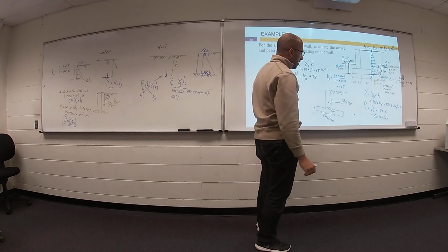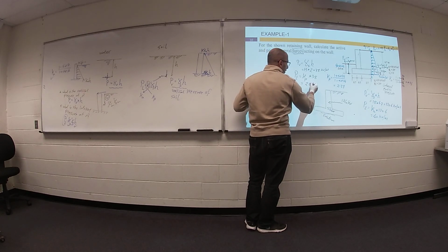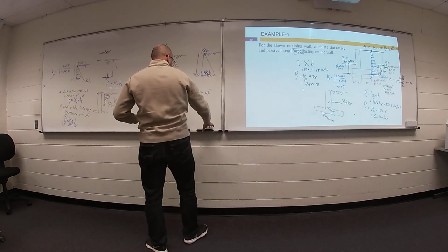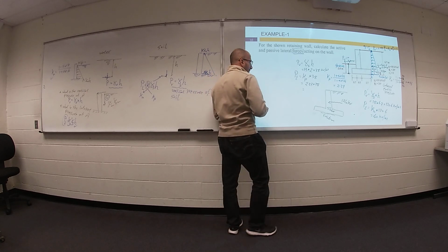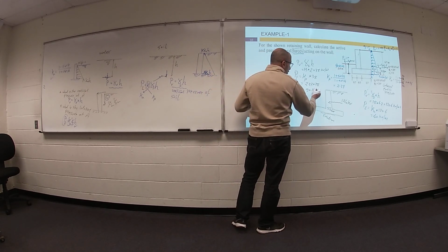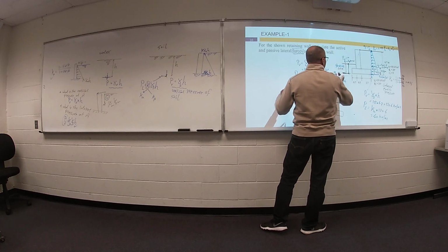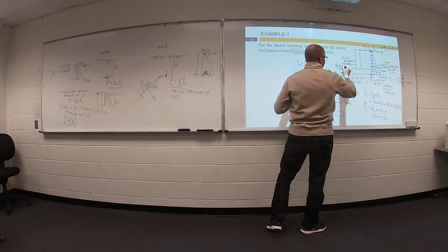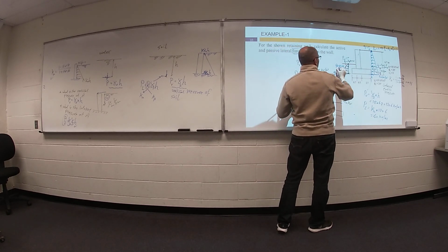What is the value of the K passive? 2.37 times 38. What is the value? 90. Sure? Okay. 90 kilonewton per meter square. So your value here is 90. This value is 0, so we have a triangle. Can you tell me how I can convert this triangle to a force?